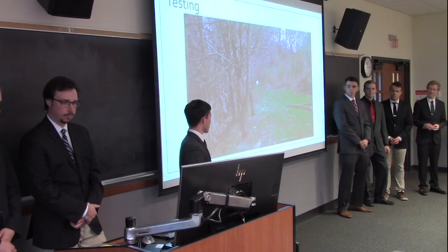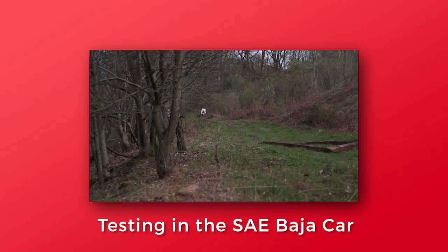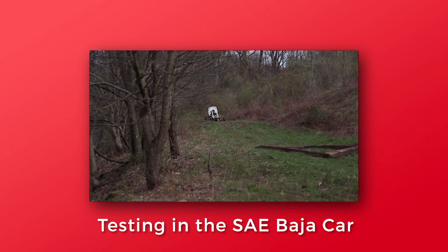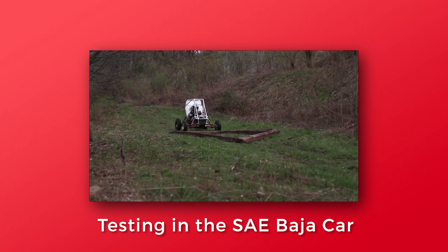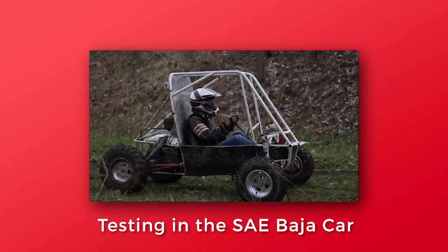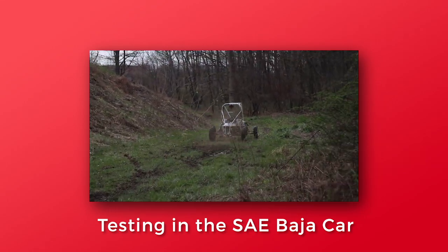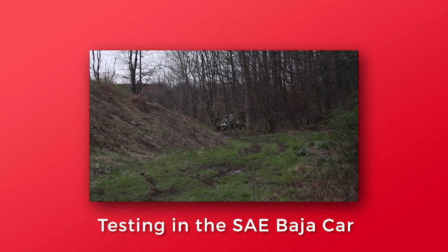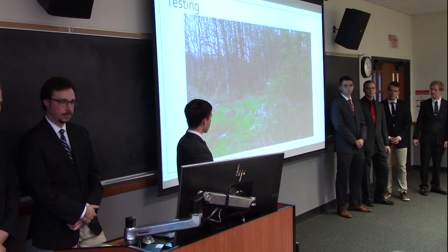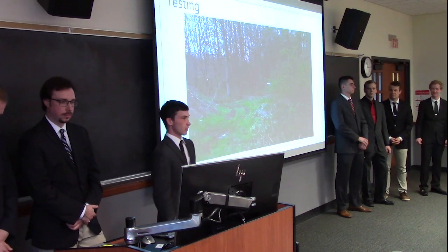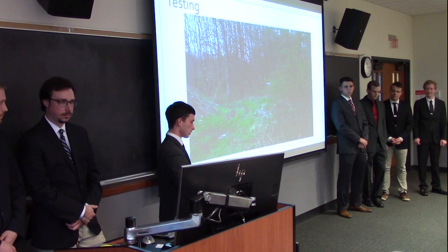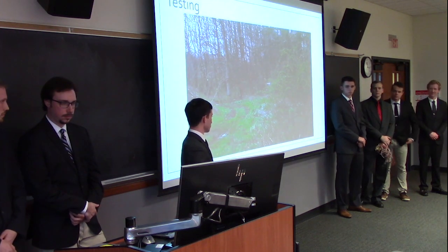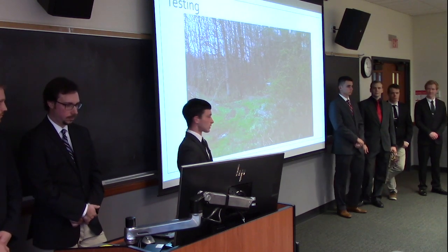To do some testing on this, we ran the vehicle over railroad ties, which kicked the back end up in the air. Anytime the rear end of the vehicle comes up in the air and then lands with torque still being applied to the wheels, it creates a massive shock loading, so we wanted to make sure our vehicle could withstand that. We also ran 20+ runs where we just positioned the vehicle from a dead stop, applied maximum engine torque, and basically saw what happened.